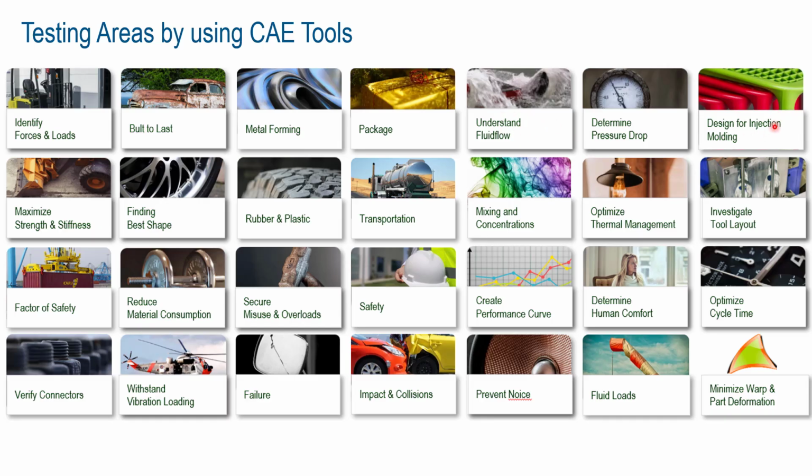And then the molding, you know, the plastic injection molds, and even the castings, right? The molten metal will be flowed, and then this kind of analysis we use, where we utilize mold flow tool for the plastics and all. Moldex also we use, and then the layouts to investigate them. So optimize the cycle time, and we have the safety.